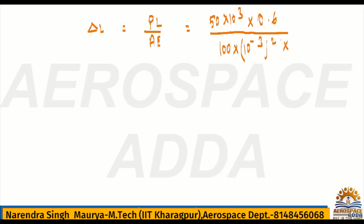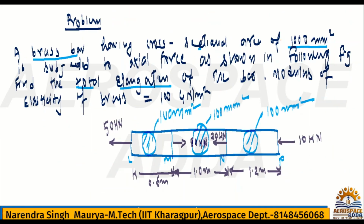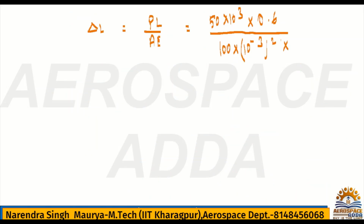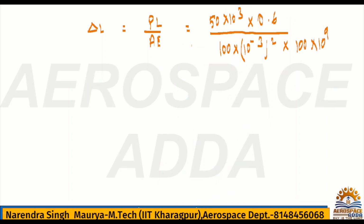Into Young's modulus, which is given as 100 giganewton per meter square. Giga means 10 to power 9, so 100 giga Newton per meter square becomes 100 into 10 to power 9 Newton per meter square. Okay, this will be the value. All right, this is one. Because we have the tensile load, the elongation will be positive.